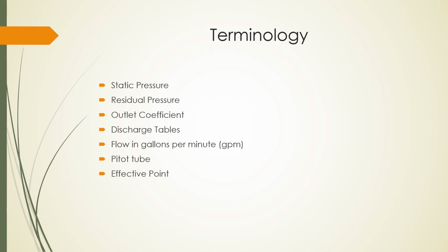And it's basically putting gauges on one hydrant, flowing another hydrant. It's actually a pretty simple operation. And from that, you should have learned a few terms, which would be static pressure, which is the no flow pressure, and residual pressure, that's the pressure when there's flow.